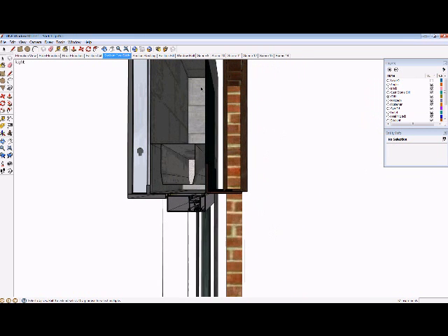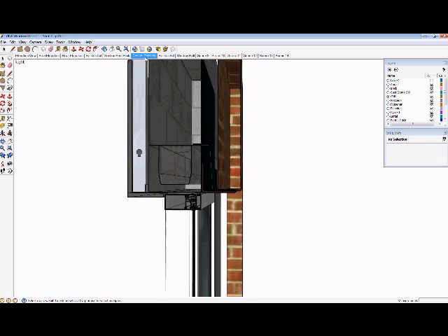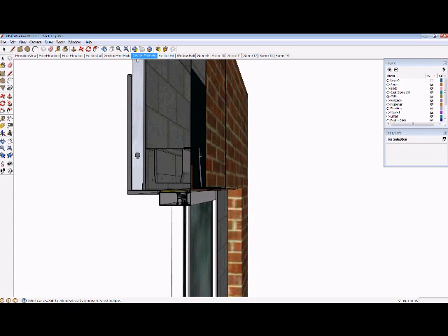You can see we have a peel and stick system that comes down the wall over the brick ledge, and then we're probably going to cut a flashing in here, as you saw in the detail previously. This is a difficult detail for us, especially on a renovation job where we have to somehow saw cut this flashing into the wall and turn it down to make sure it comes underneath the brick.